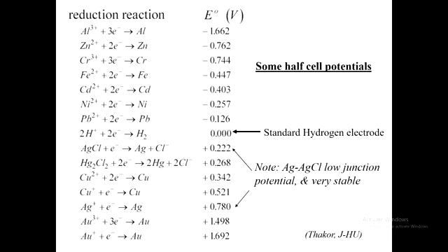When you're putting it through an instrumentation amplifier, remember that the DC potential is going to get amplified as well as any signal potential. So if you've got a high gain amplifier, then maybe a gain of 100 or something like that in the front end, that is going to try and amplify to 22.2 volts.